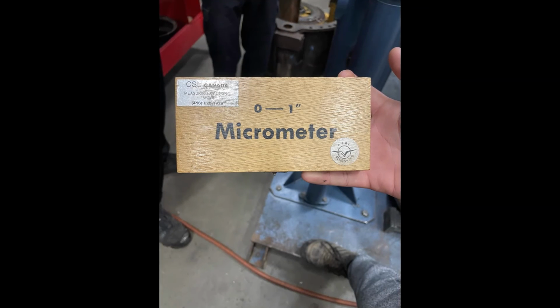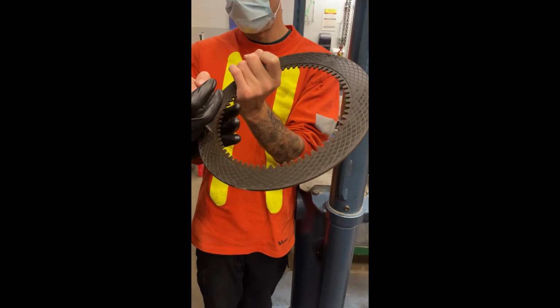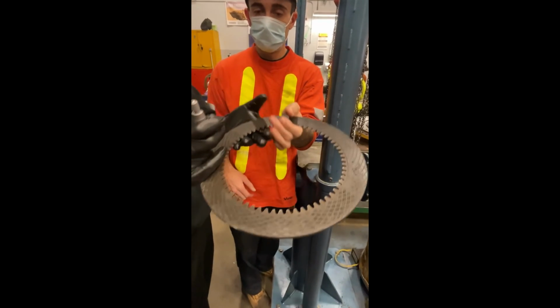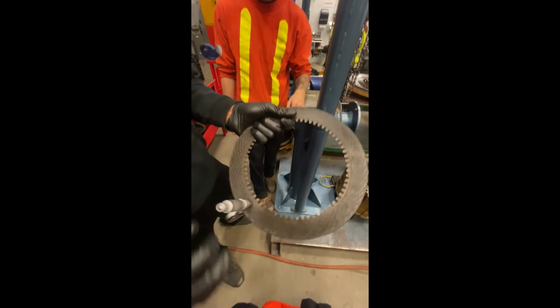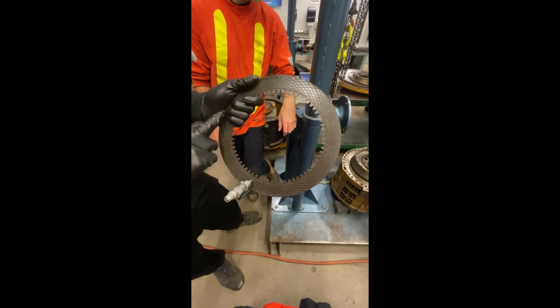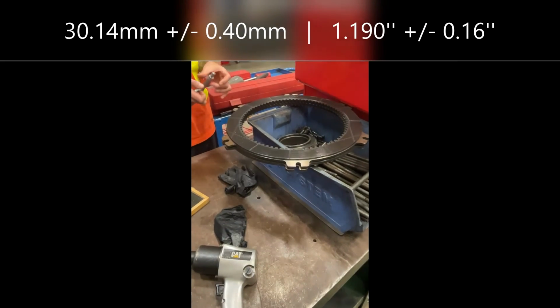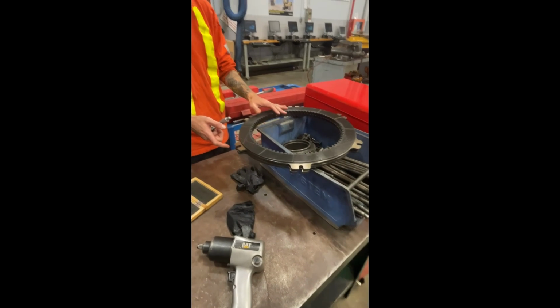Inspecting the clutch and the clutch components requires a dial micrometer to achieve an accurate measurement. The clutches should be measured separately in multiple locations around the clutch material to check for warpage and to maintain an accurate measurement. Once measured separately, the 3 friction disc assemblies and 2 clutch plates should be stacked as shown and be measured to ensure they are in spec.